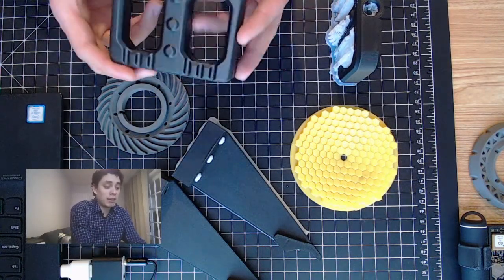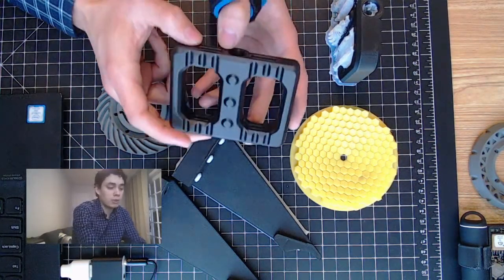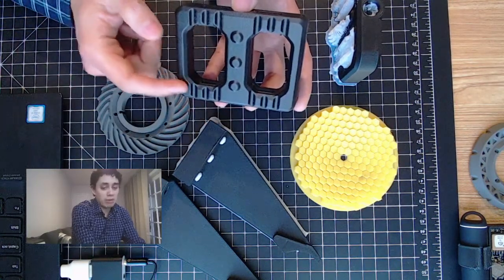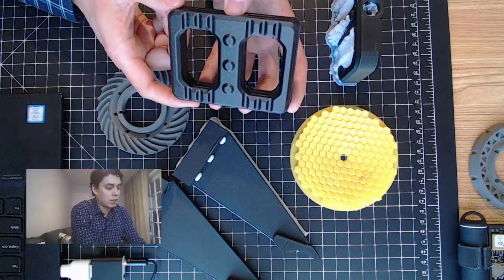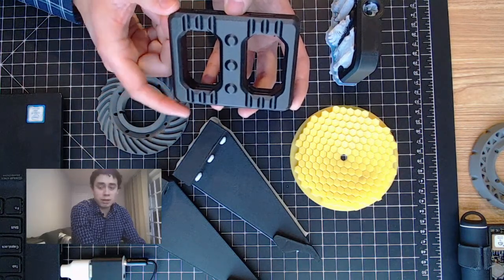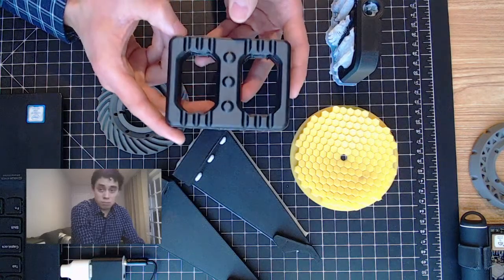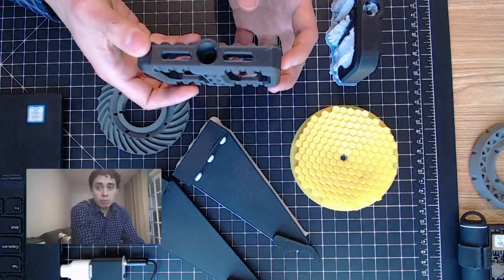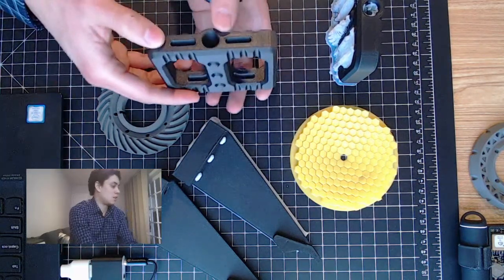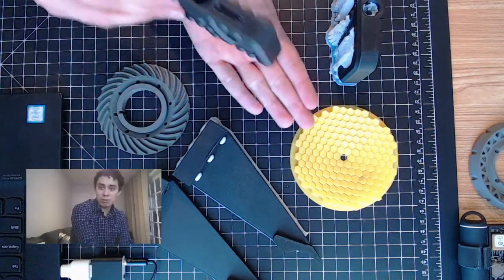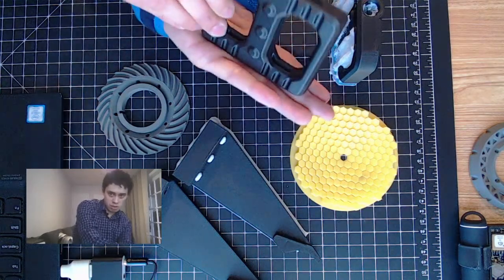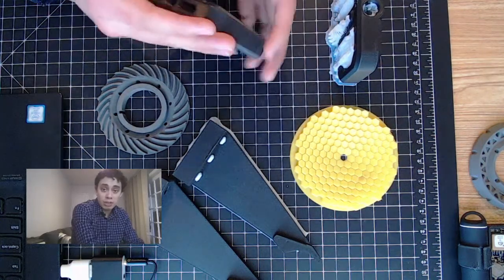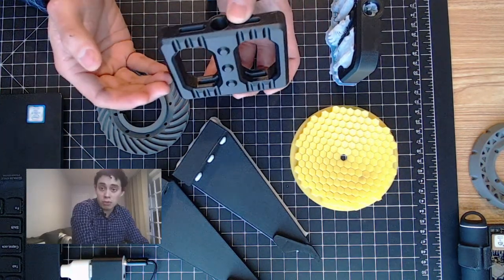And then depending on how you orient your part, you'll also be controlling and changing how those layers stack up, right? You can imagine how this object, and I'll be jumping into cloud print in a second, right? But this particular pedal, you could print it flat on its side, or I guess on its face, or completely vertical like so. So if my hand was the build plate, I could print it like so, perpendicular to the build plate, or flat against the build plate. Now, each of those orientations will have implications on the number of layers that you can achieve.